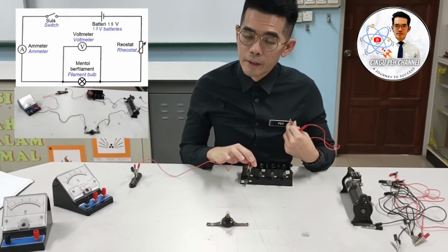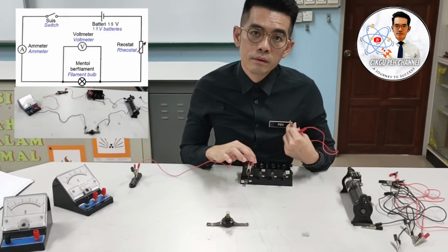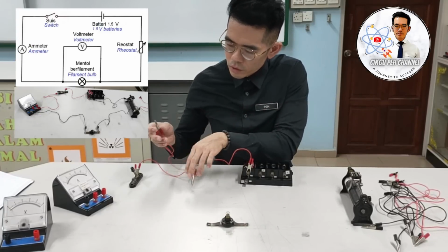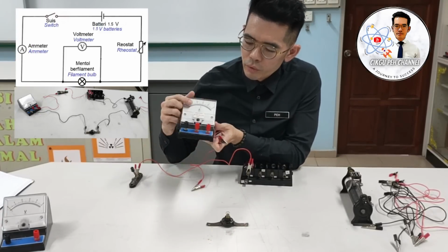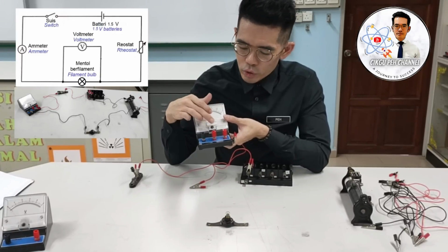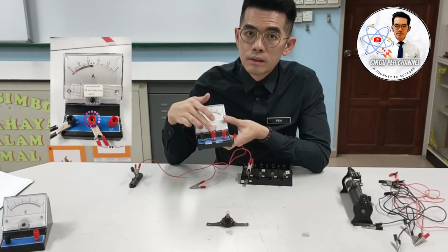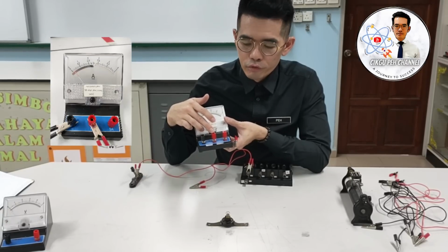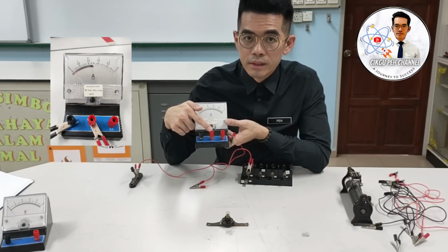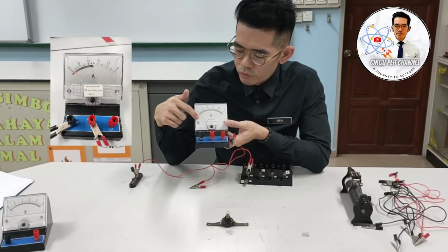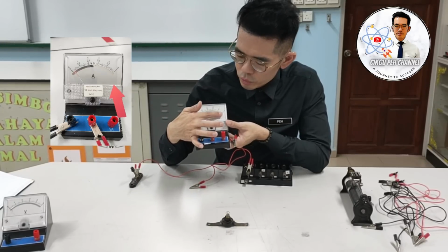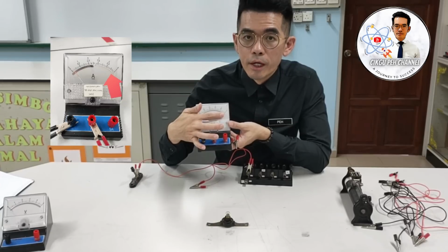And as we connect the connecting wire with the positive terminal, here we must connect the ammeter with the positive terminal, which is the red button here. And you should choose the lower ampere reading before you go to the higher. So that means here we're using the 1 ampere button. Your reading will be on the bottom scale, where the maximum value shows 1 ampere.